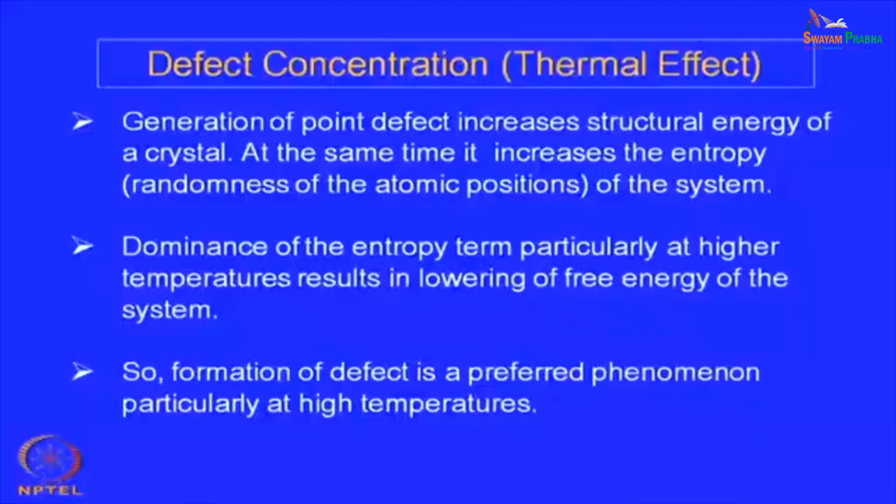It is not that defects are not allowed, defects are actually preferred, because by generating this kind of point defects you reduce the free energy of the system, since the entropy term increases, and therefore defects will automatically form at high temperature.